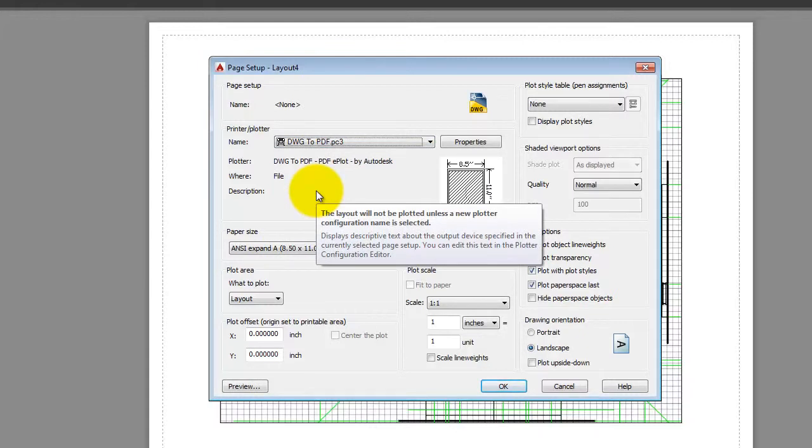It's not the ideal format to upload to the website, but it's ideal to come out of AutoCAD because when it writes the PDF file, it still keeps all of the lines as real lines. It doesn't just make an image out of it, which means that if we bring it into another program like Illustrator or InDesign, we can actually go in and edit the lines. We can add extra line weights. We can actually tweak the drawings a bit.